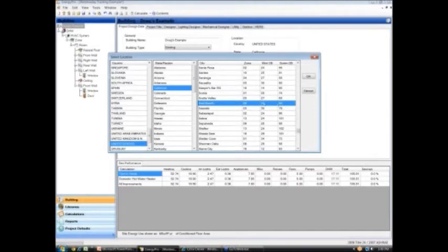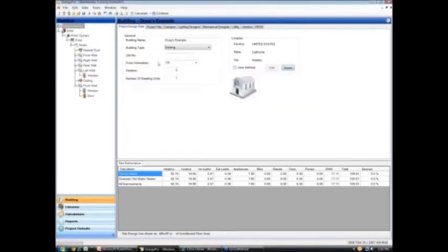These temperatures don't affect my energy consumption. Every house in climate zone 6 is assumed to have the same outside temperature. These are only used for your loads. And so if I say Shafter down in the San Joaquin Valley, it's going to have a much bigger cooling load than if I say Seal Beach on climate zone 6. Climate zone 6 is right along the coast. 13 is Fresno, south down to Bakersfield. We'll start there. So you guys, that's orientation, and this is climate zone. And you can see I've selected Shafter there.